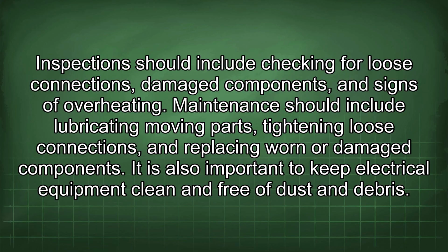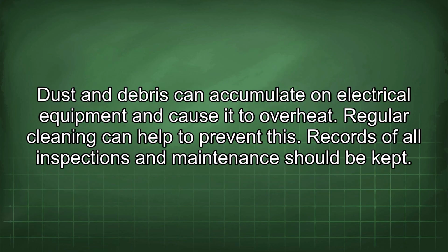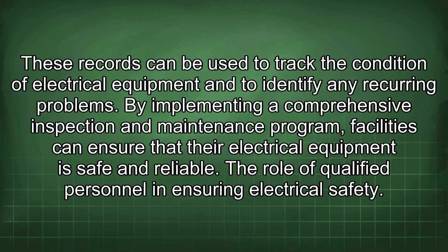It is also important to keep electrical equipment clean and free of dust and debris. Dust and debris can accumulate on electrical equipment and cause it to overheat. Regular cleaning can help to prevent this. Records of all inspections and maintenance should be kept. These records can be used to track the condition of electrical equipment and to identify any recurring problems. By implementing a comprehensive inspection and maintenance program, facilities can ensure that their electrical equipment is safe and reliable.